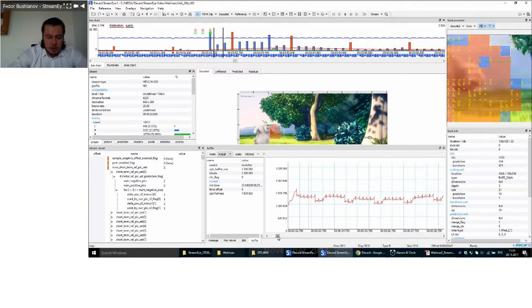So during decoding of the video picture, we want to avoid two situations. We want to avoid the situation which is called buffer overflow. Imagine it's a live video stream coming to your set-top box, and the buffer of the decoder in the set-top box is full. So there is no more space left to keep new data, and the decoder will actually skip newly coming data, and we may experience trouble, lost frames with our video stream.